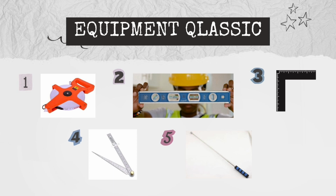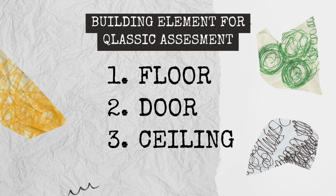Number 4, we have the steel wedge. Our group uses it to check the gap at the door by sliding it under the door and taking the reading. Number 5, we have the tapping rod. The tapping rod is used to check for hollowness in the wall and floor by sliding it very carefully on the surface. The building elements for the Qlassic assessment of this class, AP3013, are floor, door and ceiling.